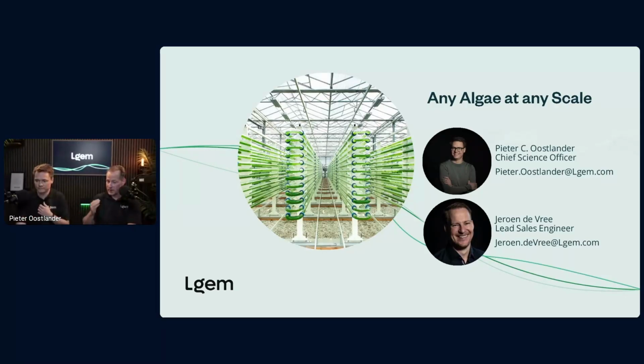So that really helps. And I saw also a question earlier about the minimum biomass concentration for inoculation. We also have some guidelines internally on that. Maybe you can elaborate a bit on that. Yeah, so typically when we scale, we want to take a small reactor to a bigger reactor. We always assume that we can do a 10 or maybe 20-fold dilution series. So if we have a reactor that is 20 liters, that is our Lab 25 system, we grow it to a high biomass concentration of maybe 5, 6, 7 grams per liter.